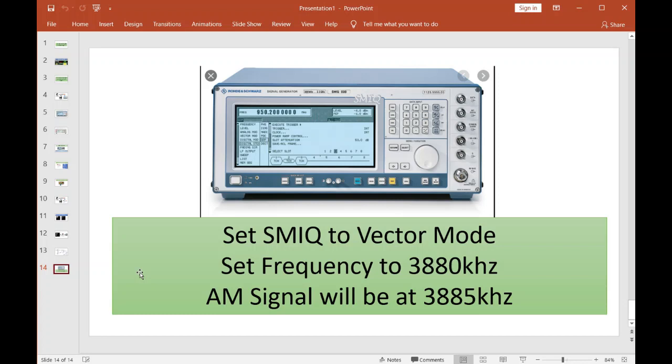Two main reasons why we did that. One, you can't send DC signals out of a sound card. Those sound signals are what's called AC coupled. So if I sent the AM signal at baseband, it would not work, okay? So that's why in GNURadio we're multiplying it by 5 kilohertz. No big deal, that's just a limitation of the sound card, but we're getting around it. And then on the other side of the AM signal will be the waterfall images.